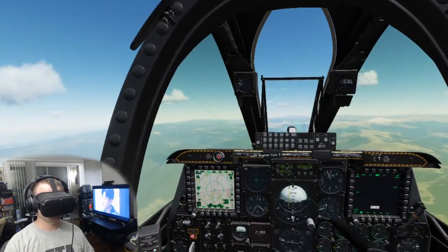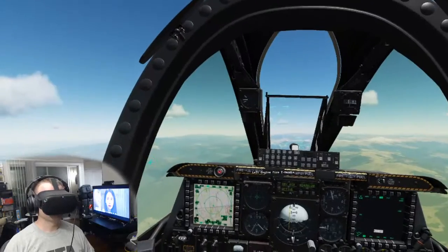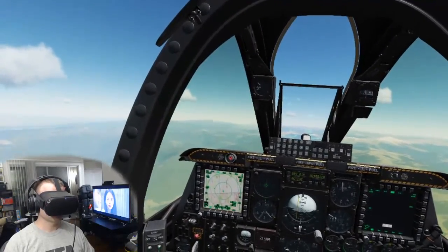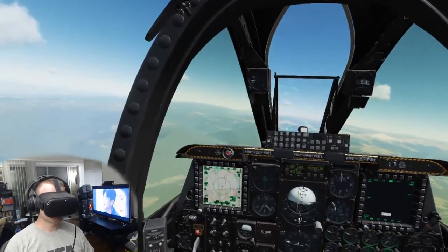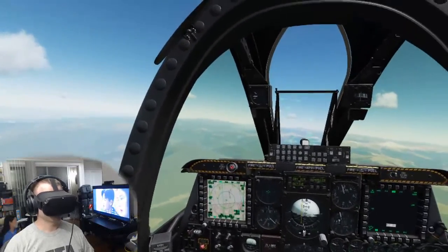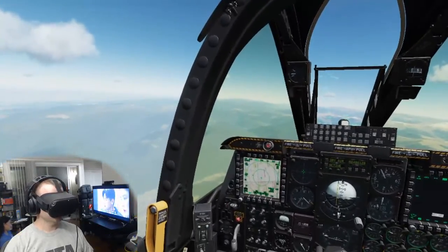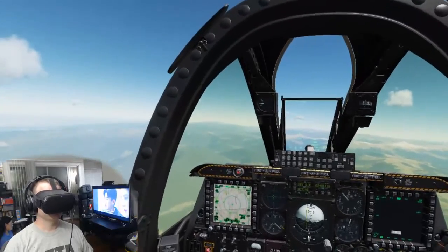Okay, now that we have control of the TAD, let's first scale the map out so we can see our entire flight plan for better orientation. To increase the TAD scale, press the HOTAS Dog Fight Switch down command or the N key on the keyboard until the flight plan is visible, 3 presses in this case.